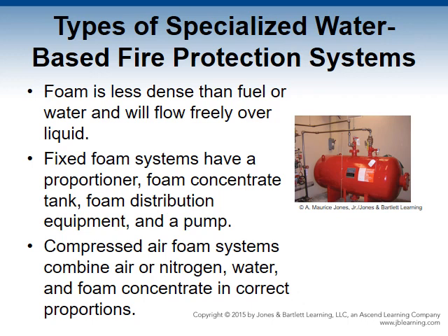You can also have a compressed air foam system, which combines air or nitrogen, the water, and the foam concentrate in the correct proportions, using a mixing chamber to combine the solution that feeds the piping and flows to a specialized nozzle that delivers the foam. Foam used by these systems are Class A or Class B low expansion foams that protect flammable liquids, liquid spill fires, and three-dimensional fires. The design and installation standard can be found in NFPA 11.